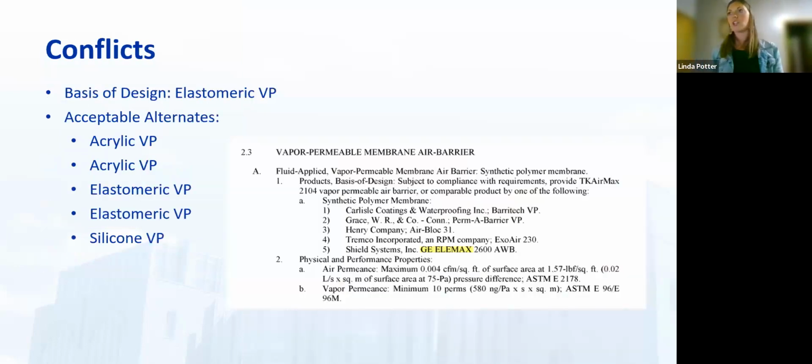So when it comes to part 2, what you're going to keep in mind is we don't want to see conflicts. If you have thought through what you want for the chemistry of your air barrier, whether it's going to be vapor permeable or a vapor retarder, whether you want high performing barriers or just a standard barrier that's going to be your everyday barrier, maybe it's mass wall in front of it, so it's not as important, it's not seeing the loads, it's not seeing UV, then you can't just put all of the barriers down and say pick one. You're not going to get what you want.